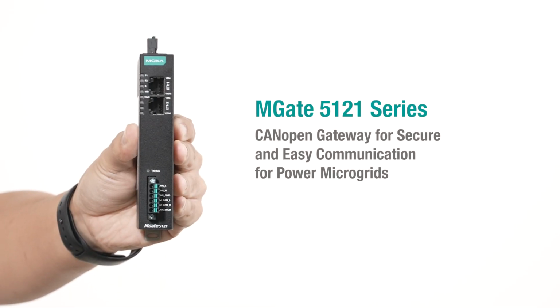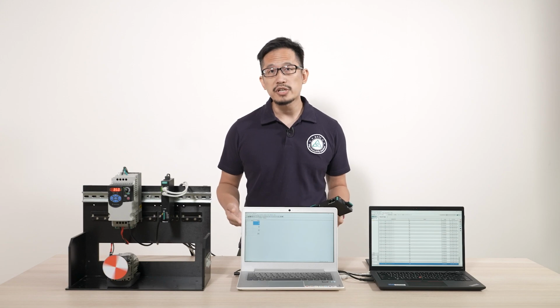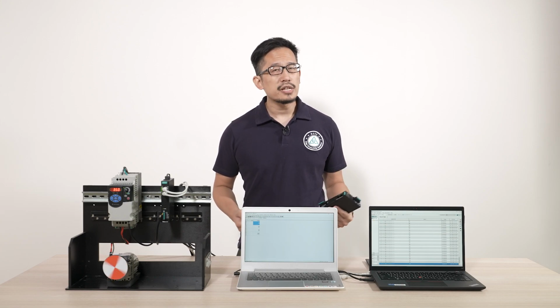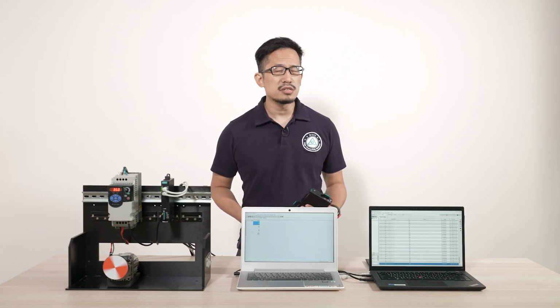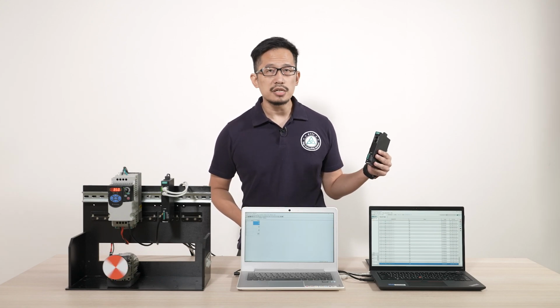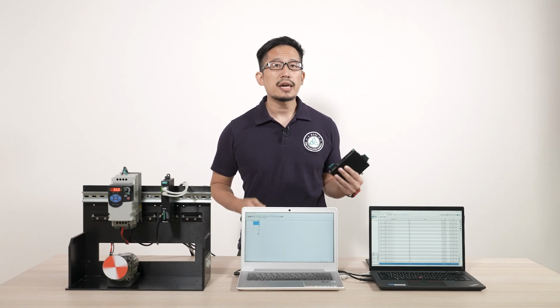The MGate 5121 series is a secure, rugged, and easy-to-use CANopen gateway specially designed for the needs of power microgrids. When you have generators, inverters, or controllers that use CANopen, but you have a SCADA or a PLC that uses Modbus TCP protocol, integrating these devices together can be complicated, difficult, and expensive. To make all of this easier for you, we designed the MGate 5121 to make CANopen protocol conversion simple and economical to implement and maintain.